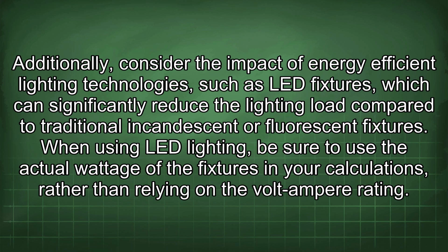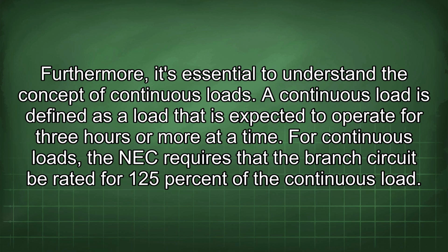Additionally, consider the impact of energy-efficient lighting technologies such as LED fixtures, which can significantly reduce the lighting load compared to traditional incandescent or fluorescent fixtures. When using LED lighting, be sure to use the actual wattage of the fixtures in your calculations, rather than relying on the volt-ampere rating.